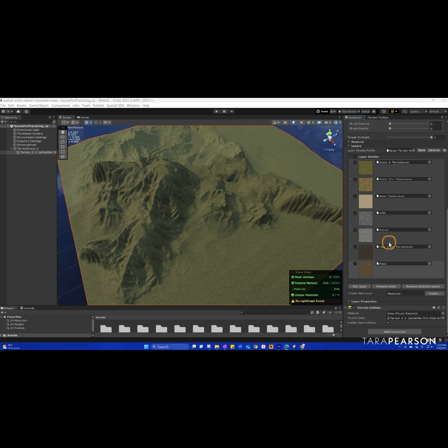The layer on top will cover the entire area of the terrain tile. To paint, select the layer you want to start with and click and drag on the terrain. Use different brush sizes, opacities to blend things smoothly.